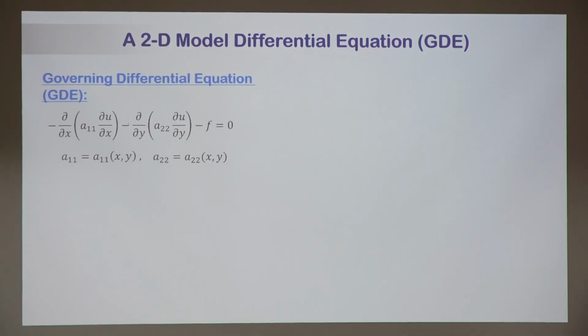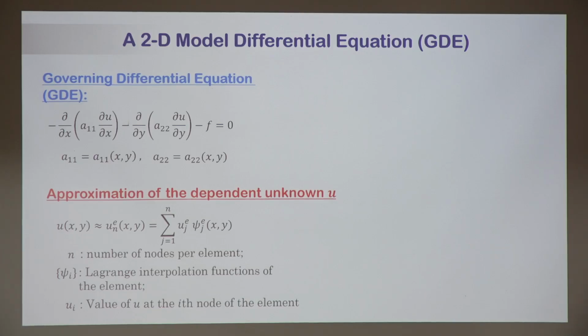It comes up in heat transfer, in fluid mechanics, in structures, name it. So if we were to solve that in finite elements, what we do is take the function and approximate it over any typical element as a series of unknown nodal values and known functions.